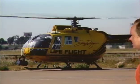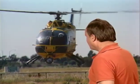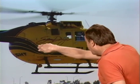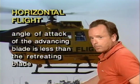Now let's take a look at a few questions the FAA asked you about helicopters. One of the questions they ask is, let's assume you're flying in this helicopter and you manage to get it in straight and level horizontal flight. And I think we're eventually going to get there, maybe, maybe not. They're going to ask you, how does the angle of attack of the advancing blade compare to the angle of attack of the retreating blade? Well, the advancing blade is actually going faster through the relative wind than the retreating blade, so therefore it has to have a smaller angle of attack. So the angle of attack of the advancing blade is less than the angle of attack of the retreating blade.